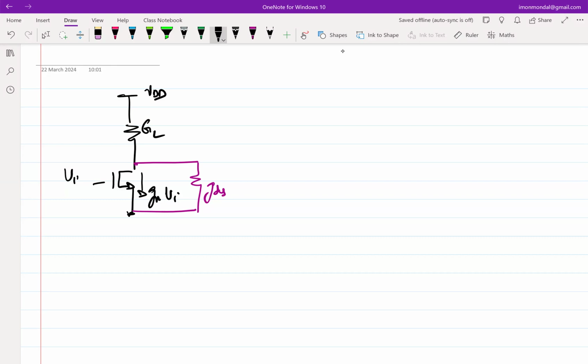So the solution that we came up with was, connecting here directly is a problem. So we cannot connect directly. So we have to put something here which can give an impedance such that all of this incremental current gm times Vi flows into that box, right? Which means we need something which has a low input impedance, low with respect to the impedance of the transistor itself.